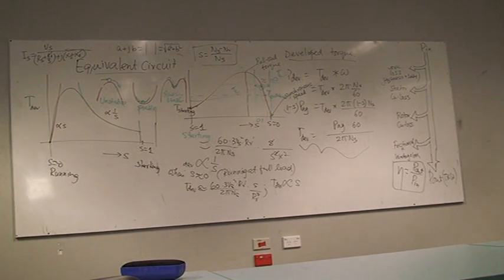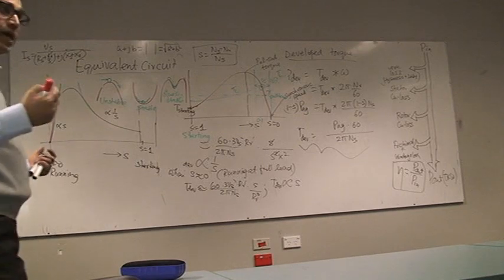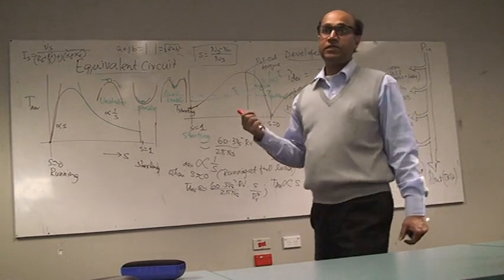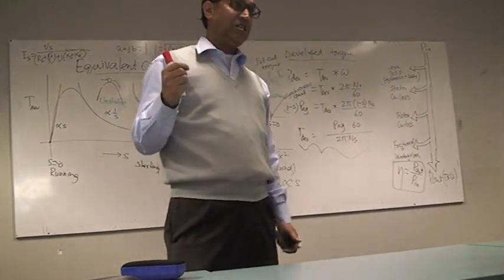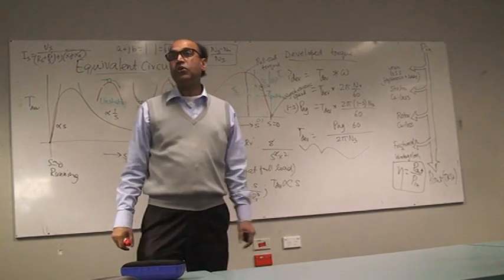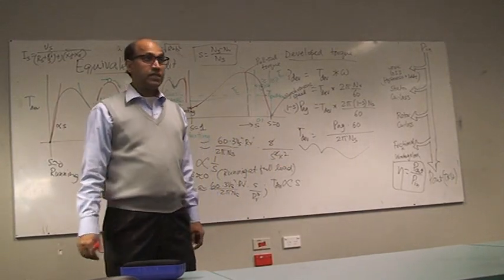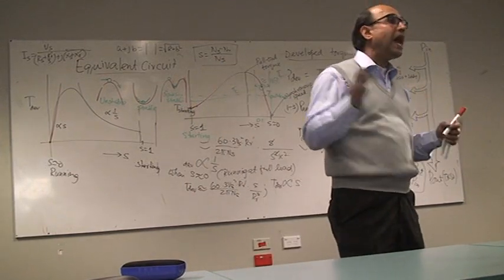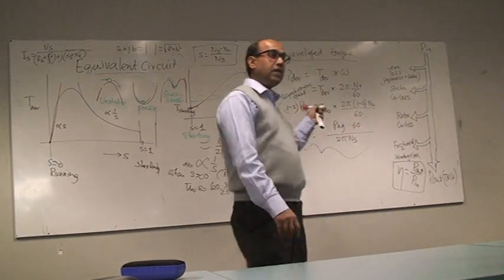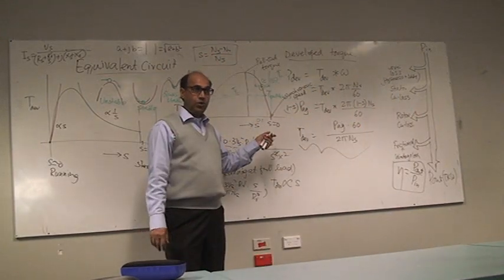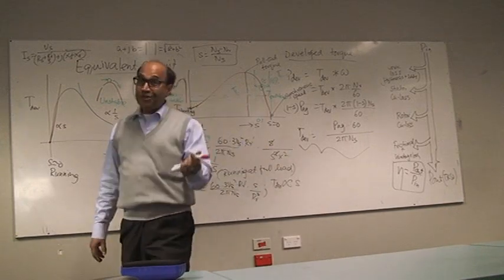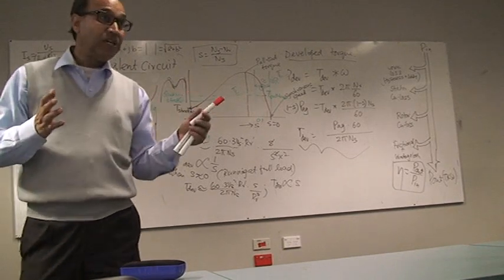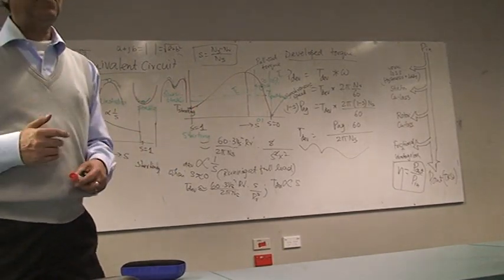That tells the problem for the induction motor too. Because it operates at constant speed, and in most applications you need the speed to change, the induction motor is not suitable for that type of application. Your application needs variable speed, and that's the reason the induction motor is not suitable for those applications. It does not mean the induction motor cannot be used. It means it needs something else to make it run at different speeds.